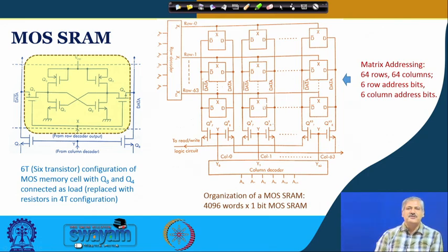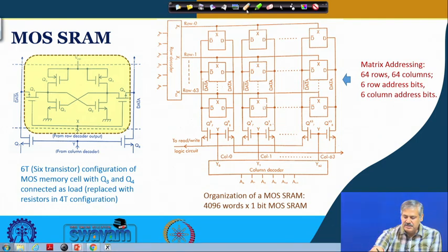Finally, MOS based SRAM. Okay. So, in MOS based SRAM, it is compared to the BJT based memory cell that you had seen. Okay. So, we had these 2 transistors there, inverter, and here instead of a normal resistor, you can have a MOS based transistor, which is a MOS based resistance, which takes less space.